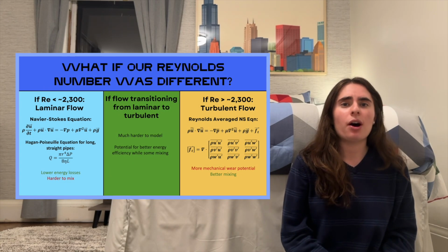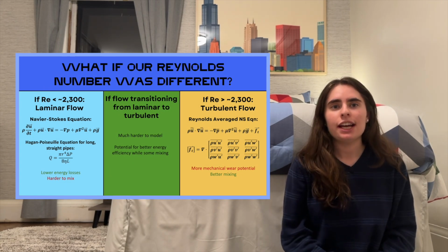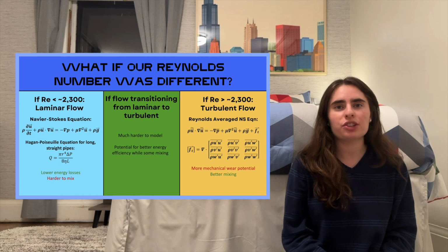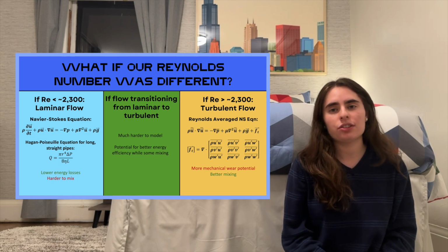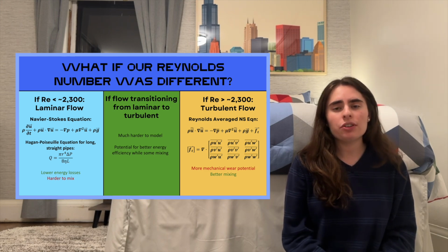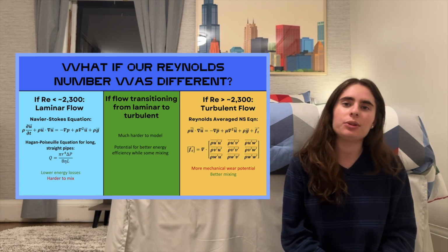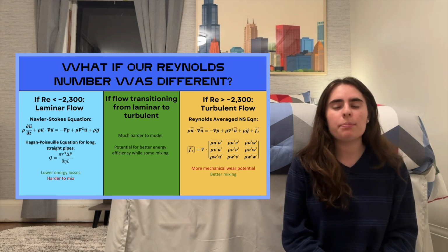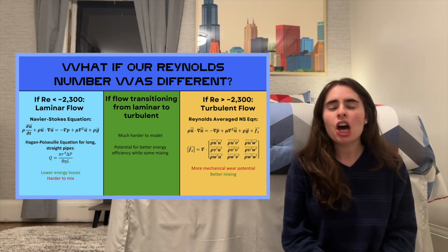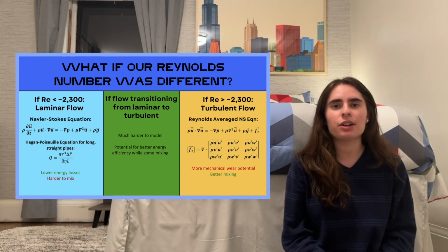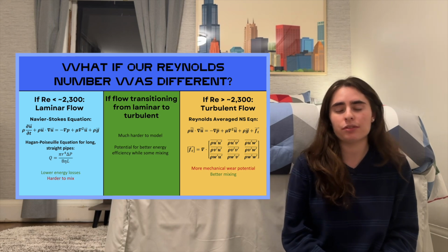Turbulent flow is hard to model because we use Reynolds averaging to add an extra term to the Navier-Stokes equation, which is Ft. Ft encompasses the effects due to fluctuations in the fluid, and we need analysis software in order to predict it. Reynolds averaging also assumes that our flow is stationary in order to decompose the velocity into its time average components, and for a piston air compressor with cyclic motion, assuming stationary flow won't fully capture the fluid's behavior. A higher flow rate with a lower pressure yields a Reynolds number that is higher and thus turbulent flow.